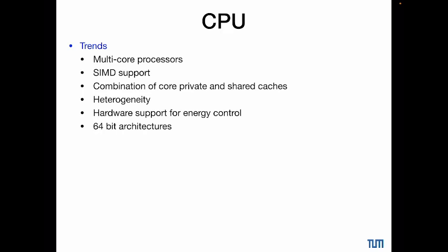Yeah? And that is definitely an important aspect for the CPU companies. They integrate higher and higher support for the SIMD operations, because data parallelism is everywhere. If you think about encoding videos or so, this is basically data parallelism. Yeah, you have lots of images, and each image you can split over cores, and then inside of a core you can work on vectors of the image. So that is an easy way to speed up applications, and so therefore they actually add this to the standard processors.